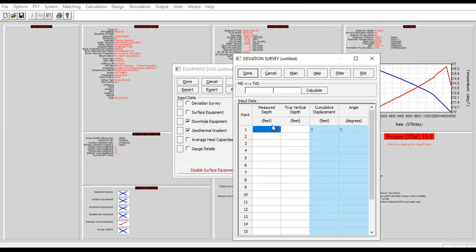You can follow my data: measured depth, MD, and true vertical depth, or TVD. 0, 0, 600, 600. Still vertical section, 1005, 1000. Starts to deviate, so we will create a deviated well here. 4075, 4000, 7700, 7500.